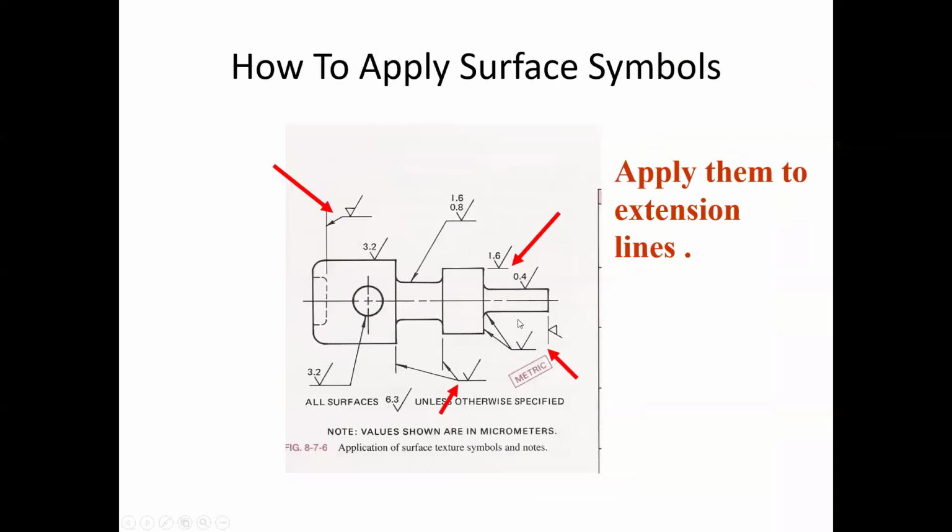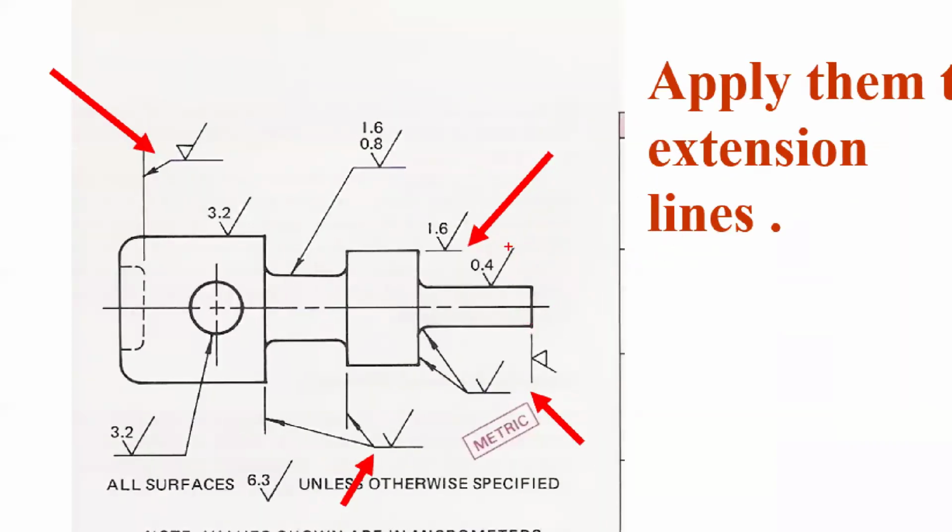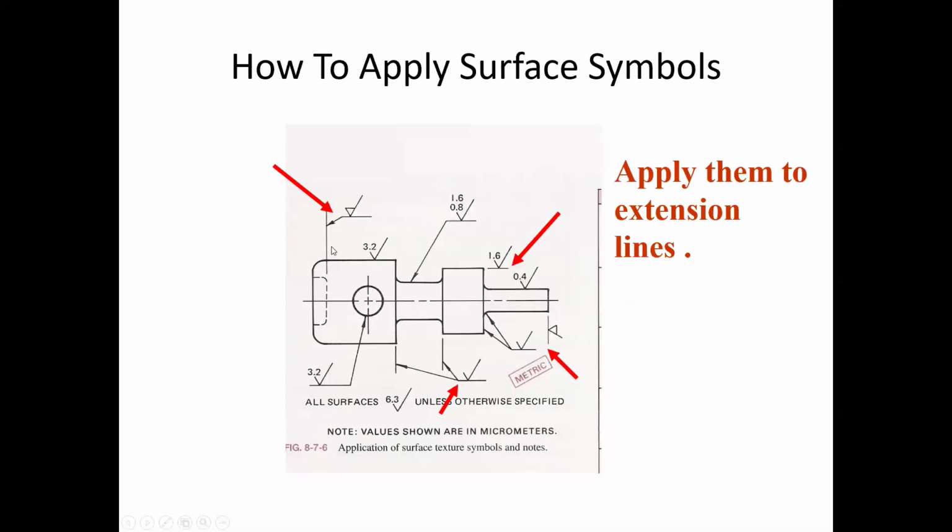All right, so very first, try to put them on your extension lines. If you had this diameter dimension out here or something like that, they might be up there closer to the part, but they're usually not. Don't put them right on top of the arrows. They're usually between the part and the arrow, and not in line with any of the other lower arrows if at all possible. Just kind of keep the confusion down.